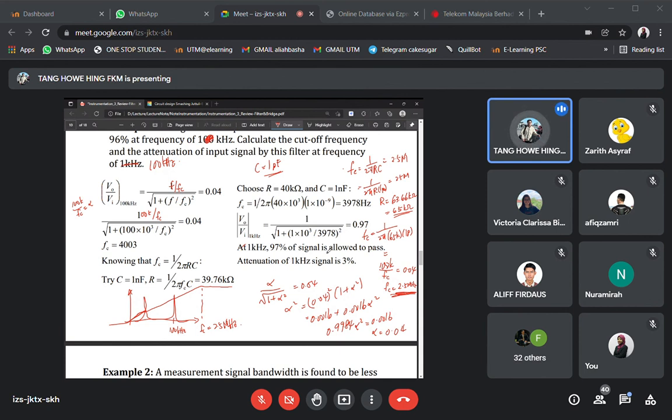Okay, so the cutoff frequency will be somewhere around 2.45 megahertz. So it seems quite close to this 2.5 megahertz. Okay, so I think I'll just use this resistor 65 kilo ohm, and the capacitor equal to 1 picofarad, 65 kilo ohm.